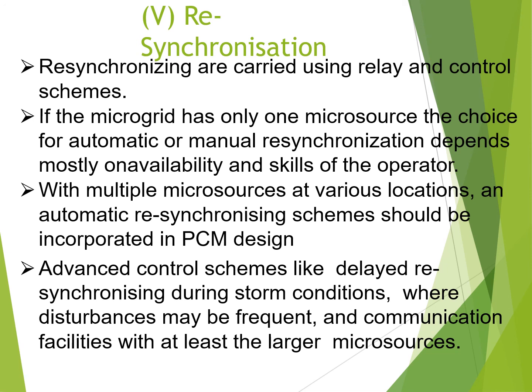And a PCM should also have some advanced control schemes like delayed resynchronizing during storm conditions where disturbances may be frequent, and communication facilities with at least the larger microsources. So with this, we come to the end of the different islanding scenarios.